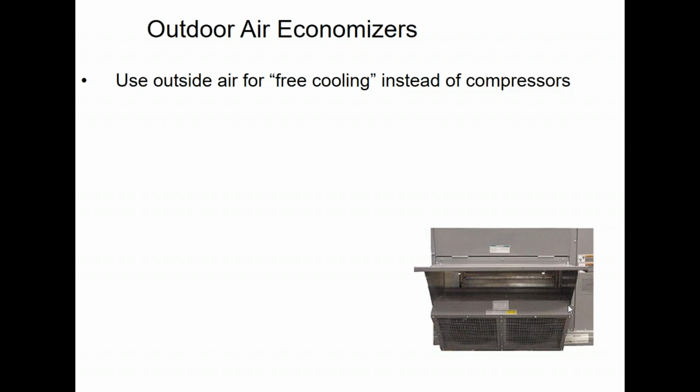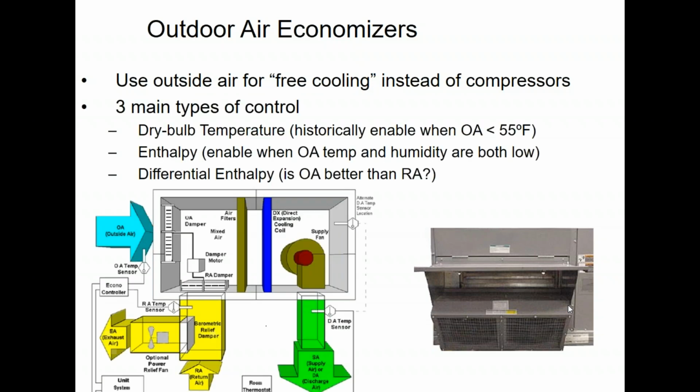It's our way of getting cooling into a building without running compressors. It's the equivalent of opening all the windows up on a nice cool day when you want the building to cool down, but you don't have any windows to open. So you open the window out there in the packaged rooftop unit and suck the cool air in that way and send it through your duct.